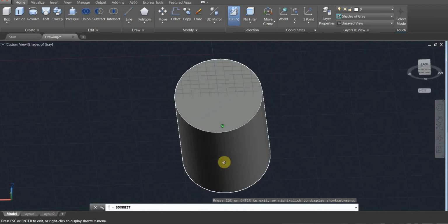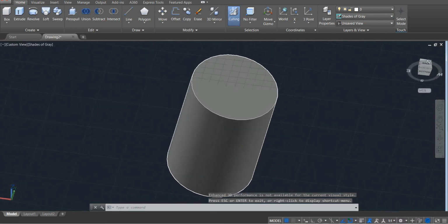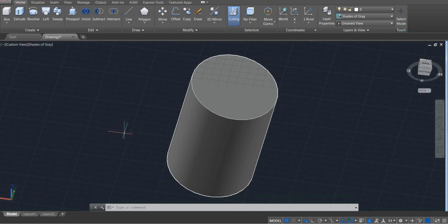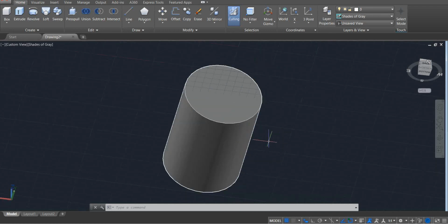As we did with the extrusion, we got the same cylinder but using revolve. So as you can see, in the revolve we use a different sketch, which is different from the extrusion sketch. For the extrusion, we draw a circle, but for revolve, we draw half of the rectangular projected view of the original cylinder. Make sense? So this is the basic idea of the extrusion and revolve commands and how we can use them for building 3D solids. These two commands are the two essential commands that you're gonna use for any three-dimensional modeling of 3D solids using AutoCAD. Make sense?